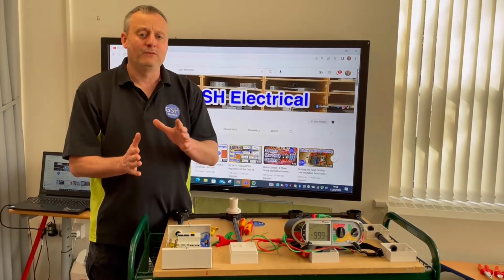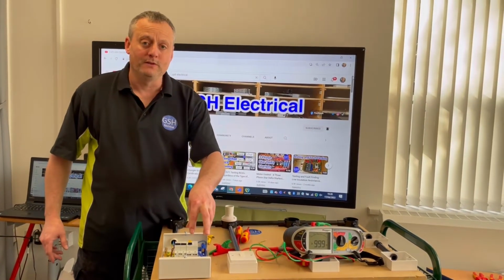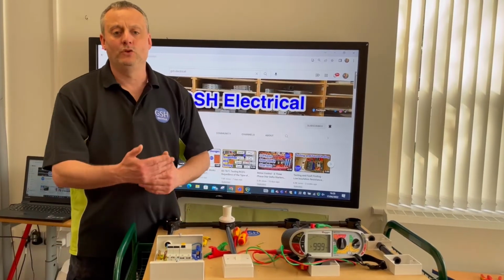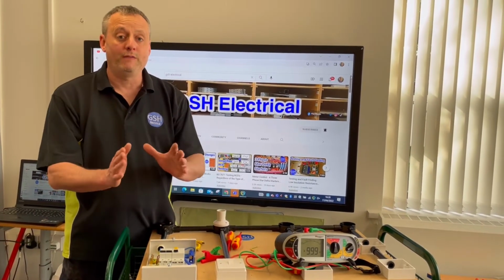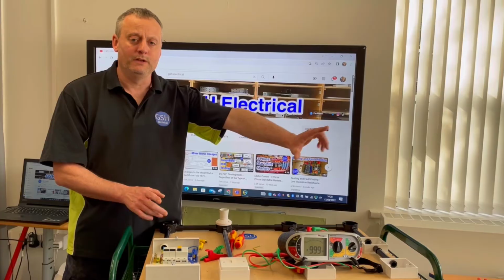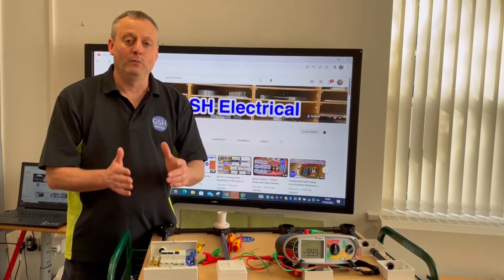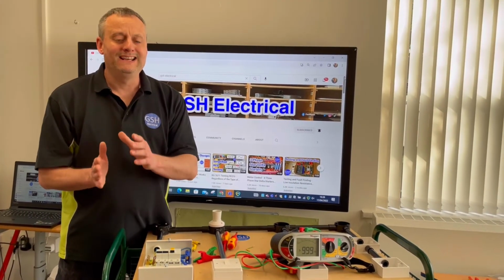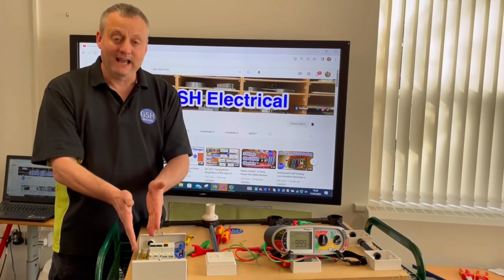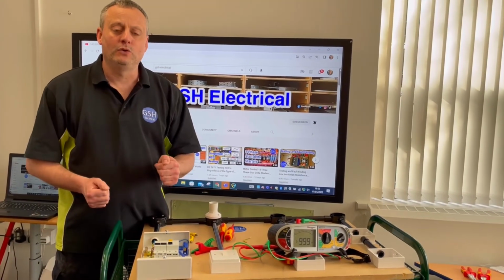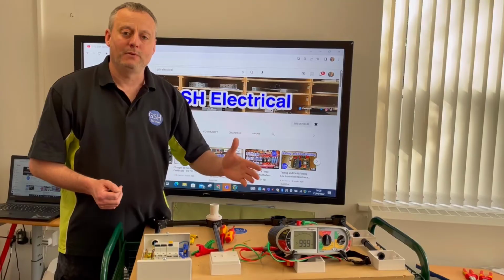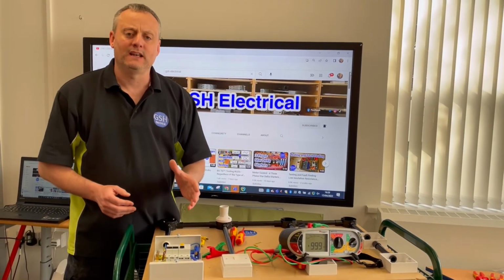We were a little bit careful with that test because obviously there are electronic components in our RCCB, and we made sure that our devices within the consumer unit were off. The power wasn't connected to the consumer unit, but we started discussing the fact that we do need, in the real world, a connection to the source earth, and I simulated that with our earthing conductor being installed and protective bonding if it was in place. So all of those need to be in place when carrying out the insulation resistance test.